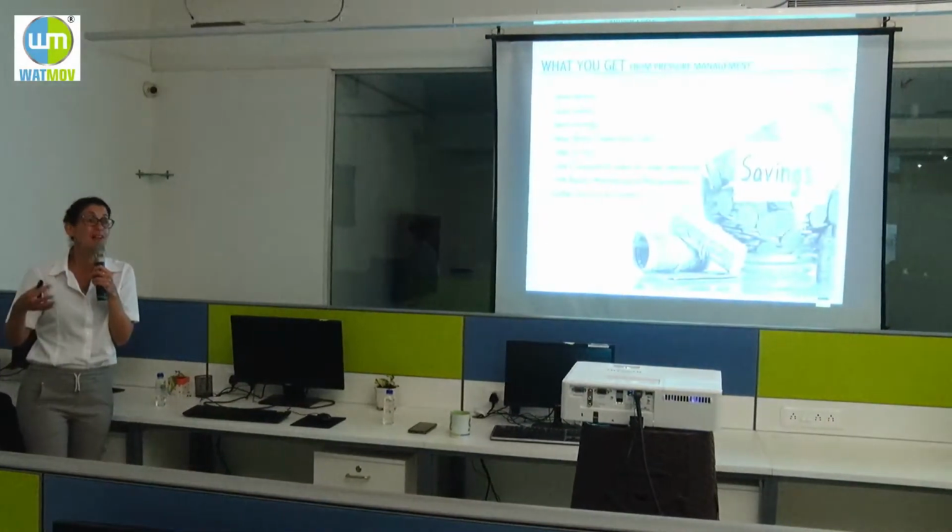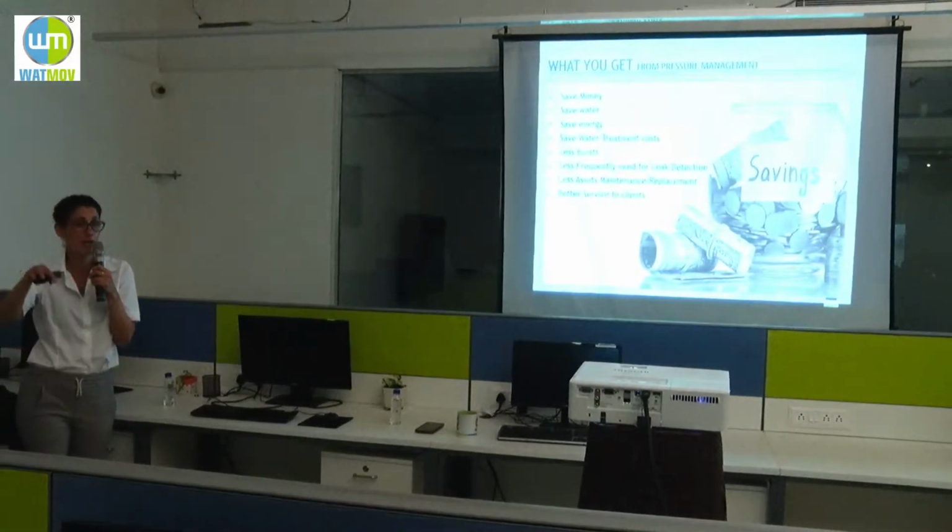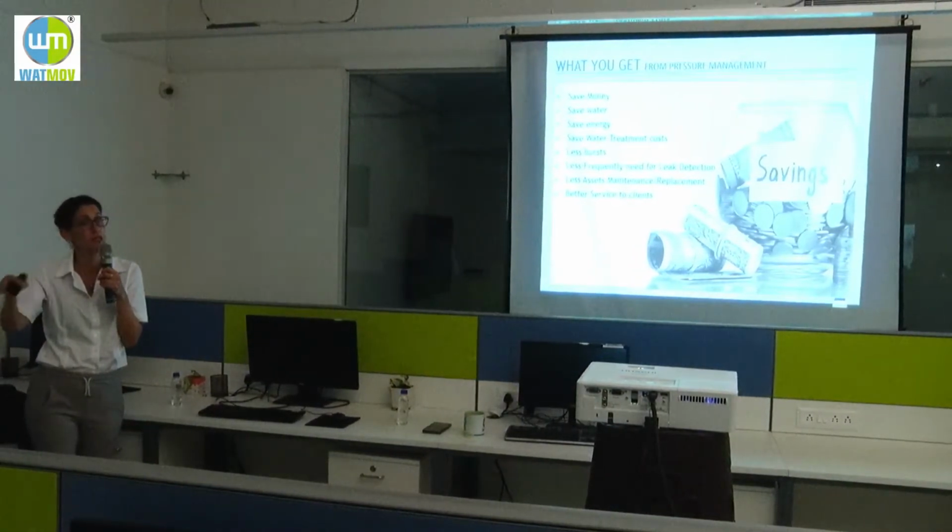So why do we want pressure management? I already said partly to save money, to save water, to save energy, to save on maintenance. If we have pipe bursts, for example, we don't need to frequently detect the leakages, because one of the solutions is to use methods to detect the leakages and fix them. We prefer to prevent it, okay, by optimizing the pressure in the DMA, okay?